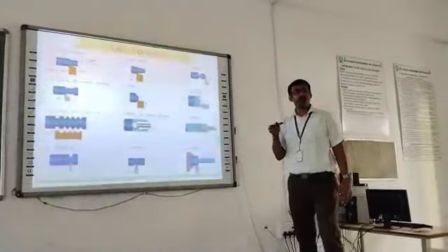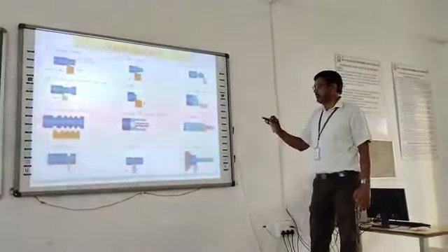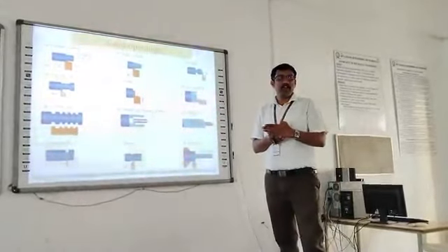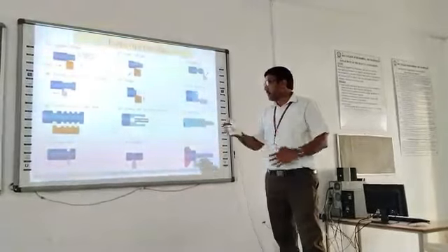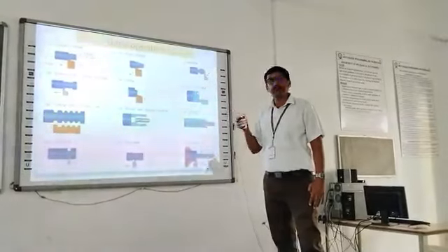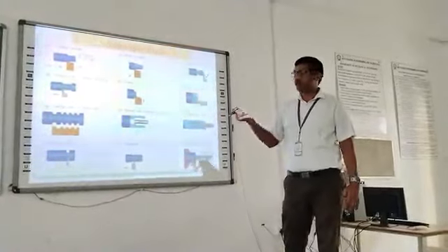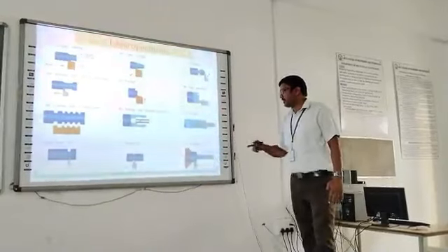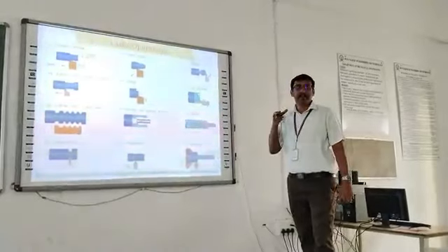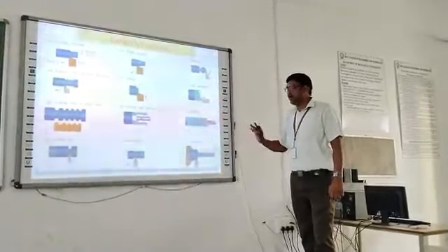Drilling is simply putting a hole in a workpiece. Next is cutting off, cutting the cylindrical job. Then it is the threading operation, where you can give a helical groove in the job. The last one is knurling, where you can make a gripping surface on the workpiece.